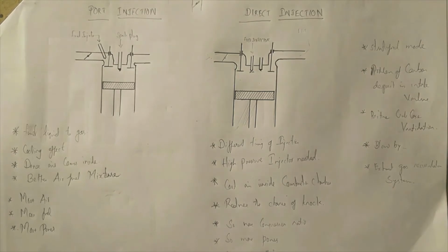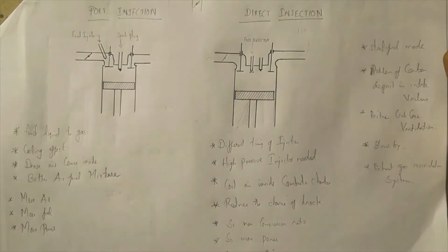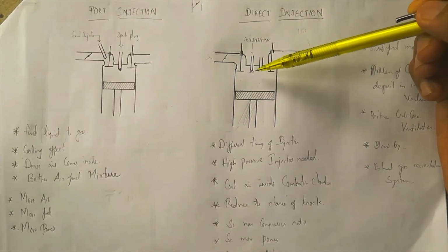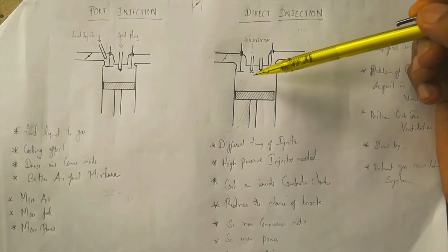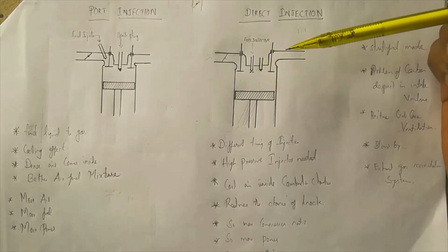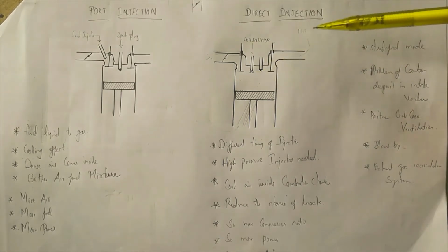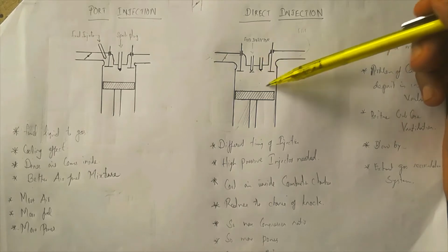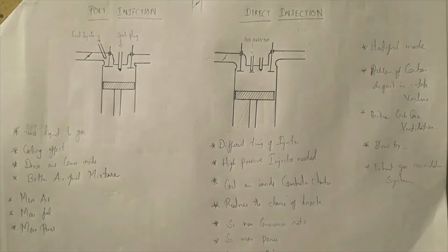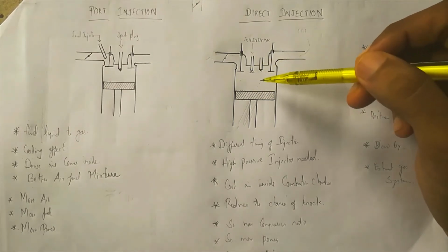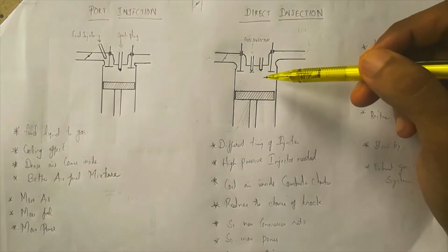So why have we switched to direct injection? The first reason is that, as I mentioned before, when we inject the fuel, it is in liquid form. This liquid evaporates and forms a gaseous state, right? When this transformation happens, it cools down the surrounding air. Cooling the surrounding air makes the air more dense, and the inside of the combustion chamber is getting cooled.